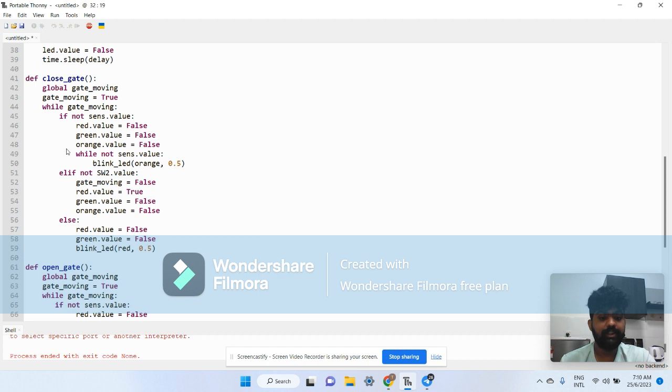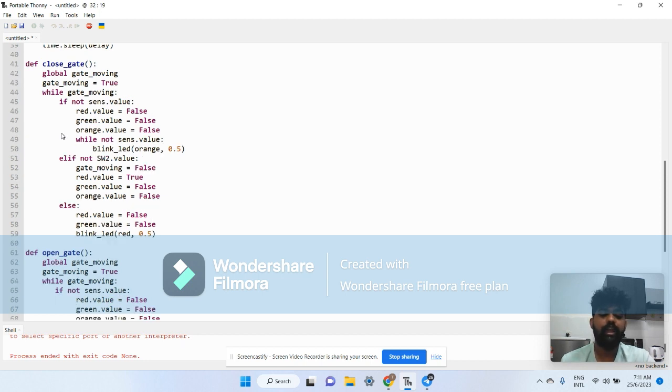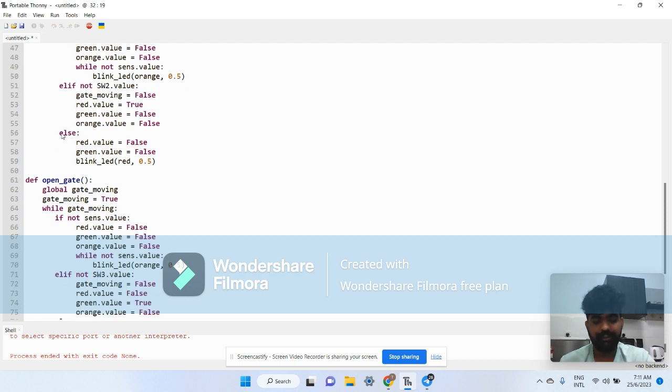While true, inside the loop it checks the status of SW1, the first switch. If it's pressed, it checks the status of gate open. If gate open is false, then it sets gate open to true and calls the close gate function. If gate open is true, it sets gate open to false and calls the open gate function. After each iteration of the while loop, there's a time sleep of 0.2, which is a pause in the execution, or a delay, of 0.2 seconds.